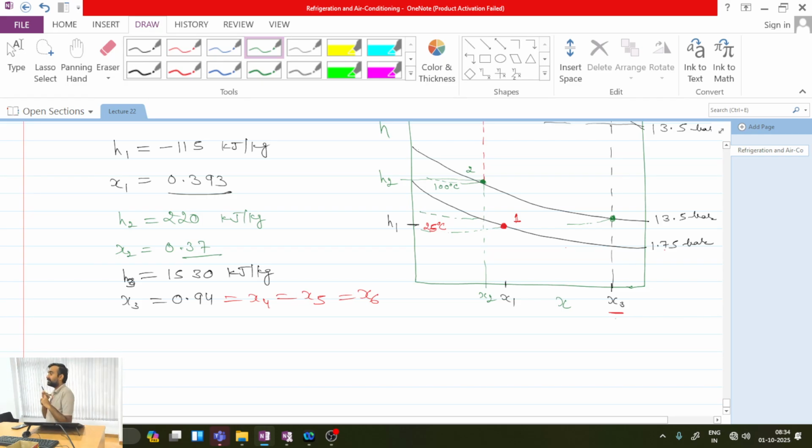So in this case, if I assume my condenser is an ideal condenser, then one data is redundant. Basically, temperature data is redundant over here, because for a saturated state in a mixture, only two properties can specify. So one property I was knowing composition, other property I was knowing pressure. So that would have served the purpose.